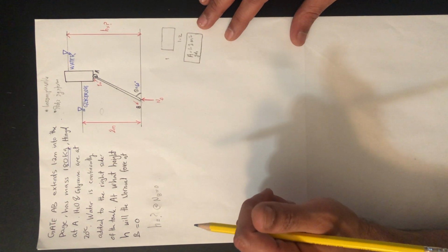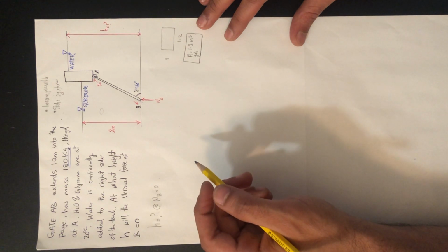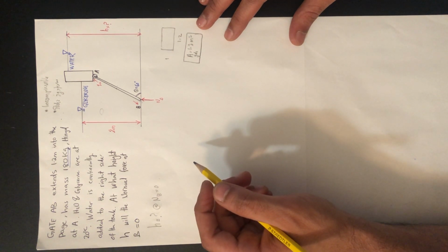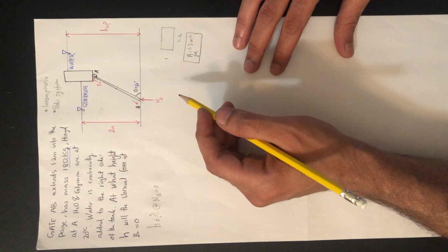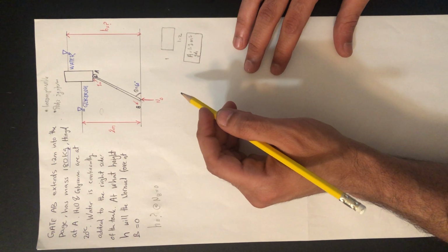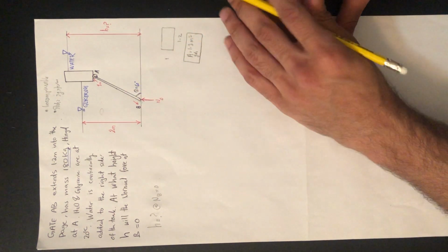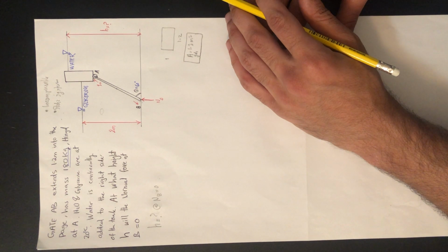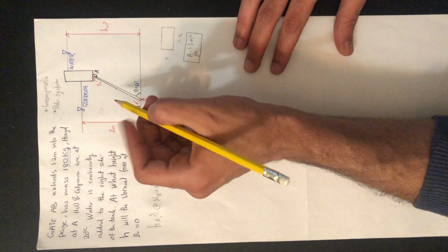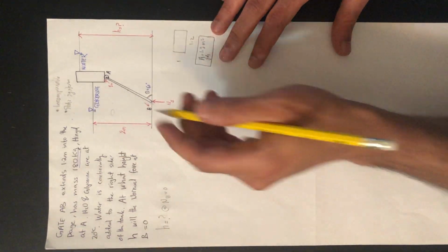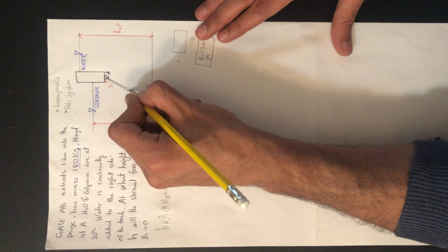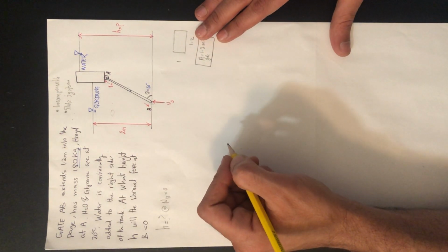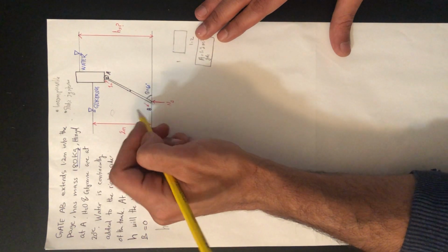Another important axis to establish before tackling the problem is the center of gravity of the gate, our surface. The geometric center of our surface, or our centroid, is half the base, because our geometrical shape here is a rectangle.